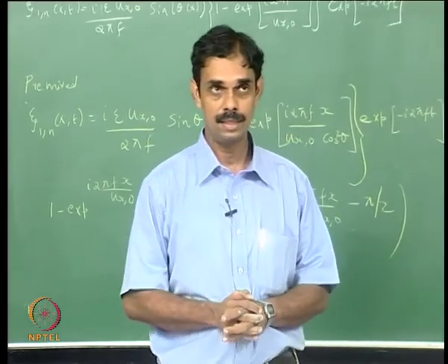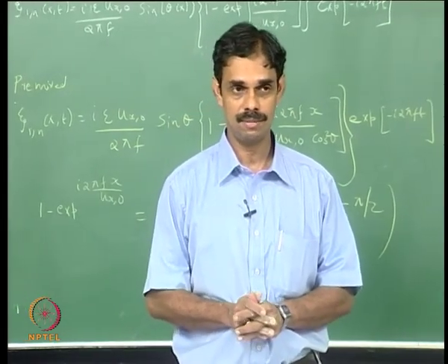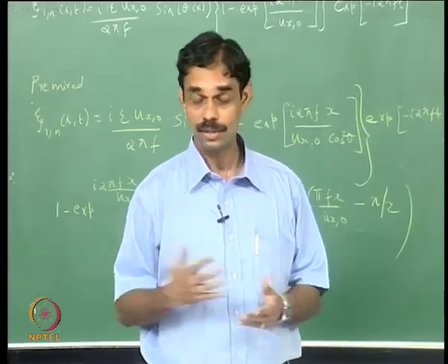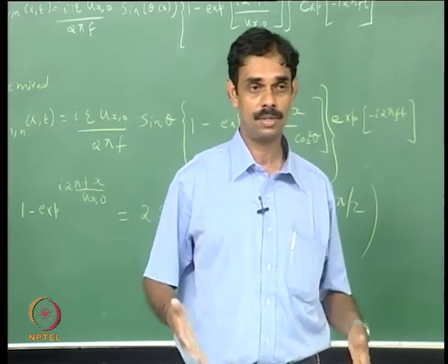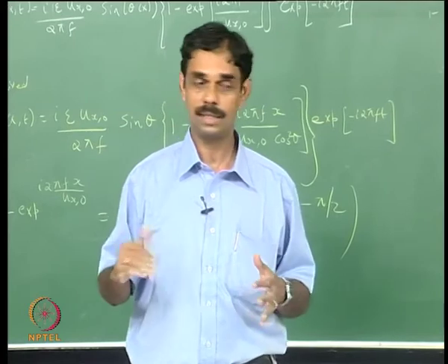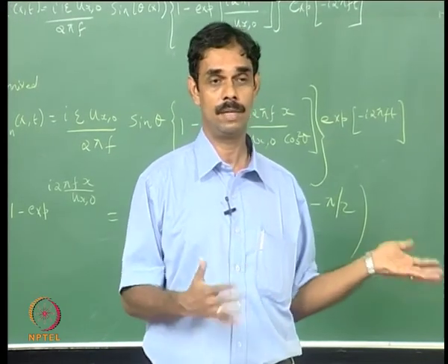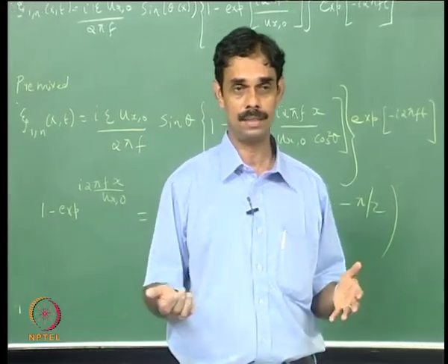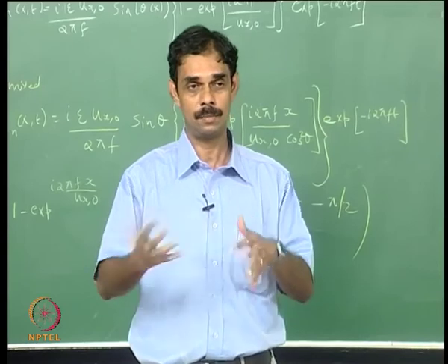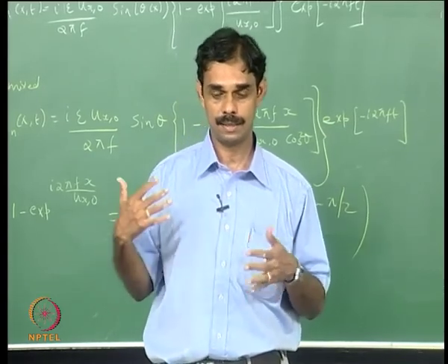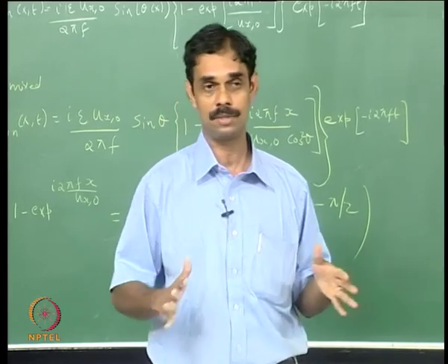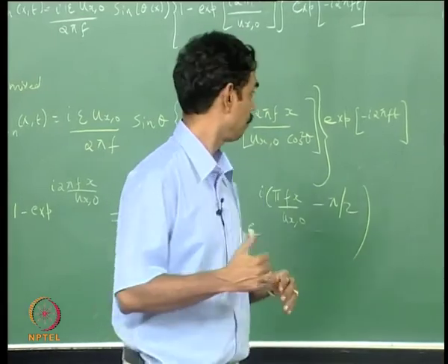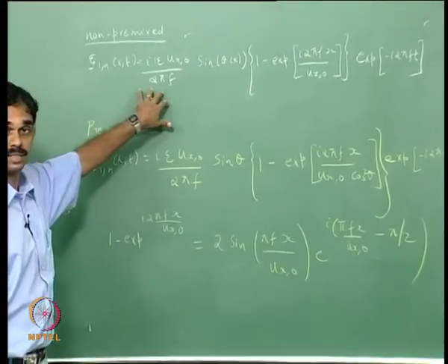First of all, in the analysis the main difference was that G really has meaning only at the flame, whereas Z we have to solve for the whole field. So we actually solve for the whole field, and from there we look for the stoichiometric surface, and then we calculated how the flame is responding, and then we got the flame response, and the flame response also behaves in a very similar way to the premixed flame, that is you have a spatial pattern which is moving, but the difference is that here it is only the convection, because the flame itself is not propagating, whereas premixed flame is propagating, so that shows some difference. So you can see in these two expressions the commonalities and the difference.